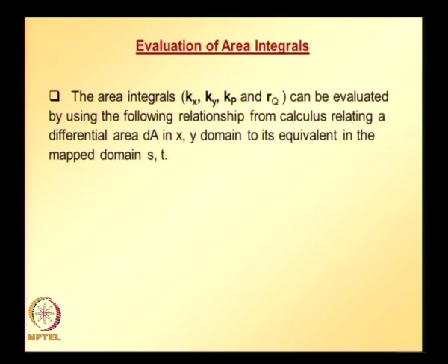Area integrals kx, ky, kp, rq can be evaluated by using following relationship from calculus relating differential area in xy domain to its equivalent in the mapped domain SNT. So, we are working for the actual element in xy domain, and that actual element we are going to map onto a parent element which is in SNT domain. So, we need to know what is the relationship between the differential area in xy domain and its equivalent differential area in mapped domain SNT.